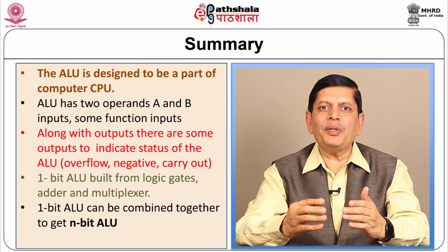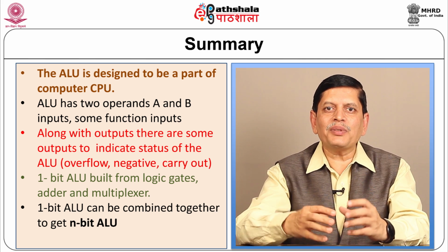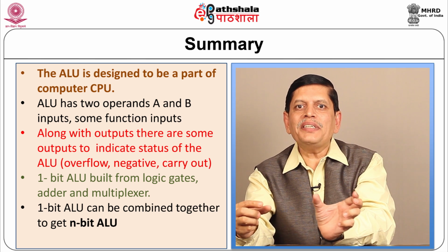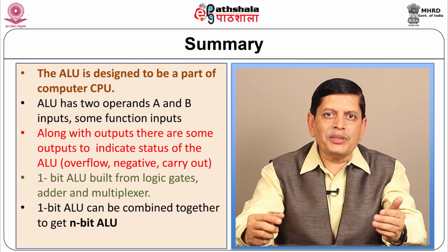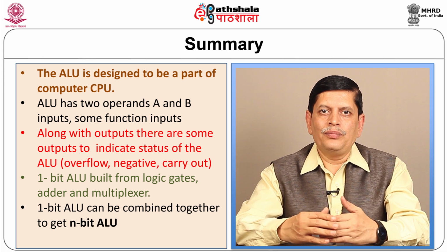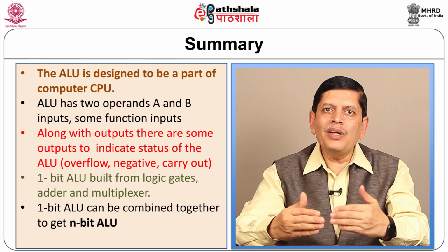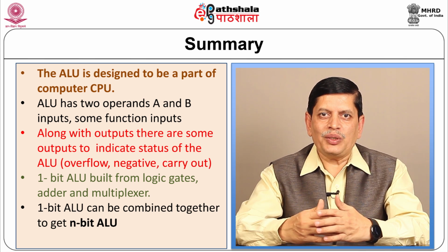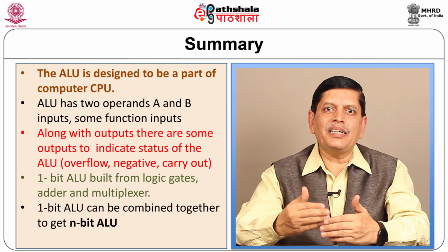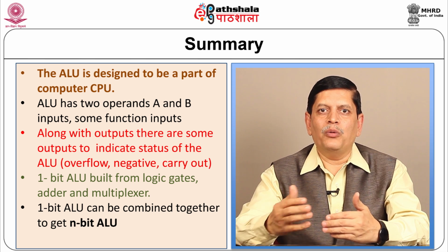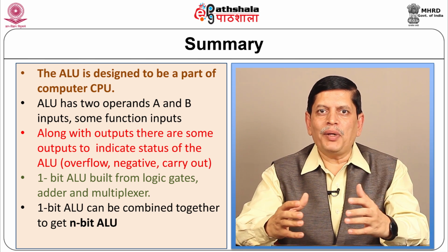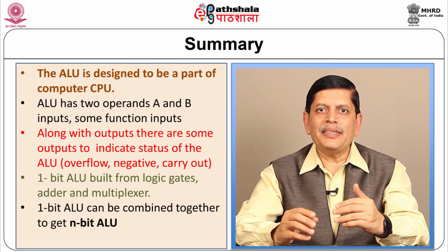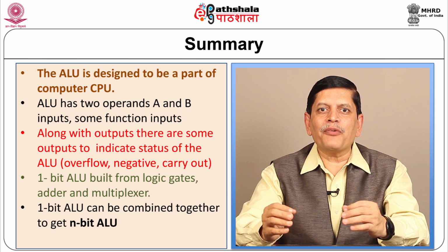The concept of the 1-bit adder is repeated 4 times, that means the same unit is repeated 4 times, and cascading along with the carry input can allow you to design a 4-bit ALU. This 4-bit ALU will have once again similar features of arithmetic and logical functions. The same concept could be extended further to an n-bit ALU. Now, while designing the n-bit ALU, we have studied a simple 6-step procedure, and that procedure is clearly defined.